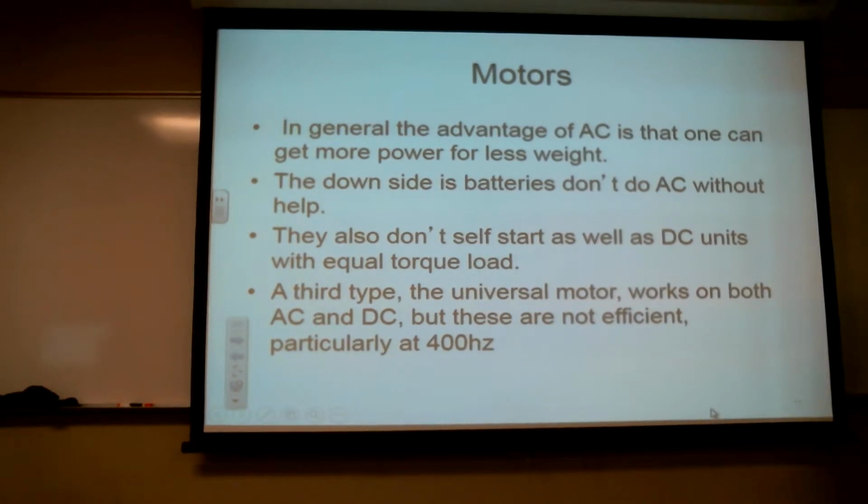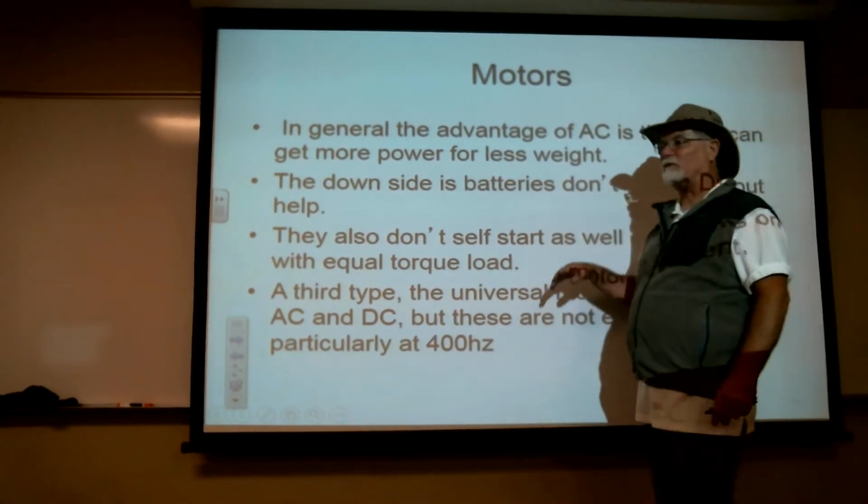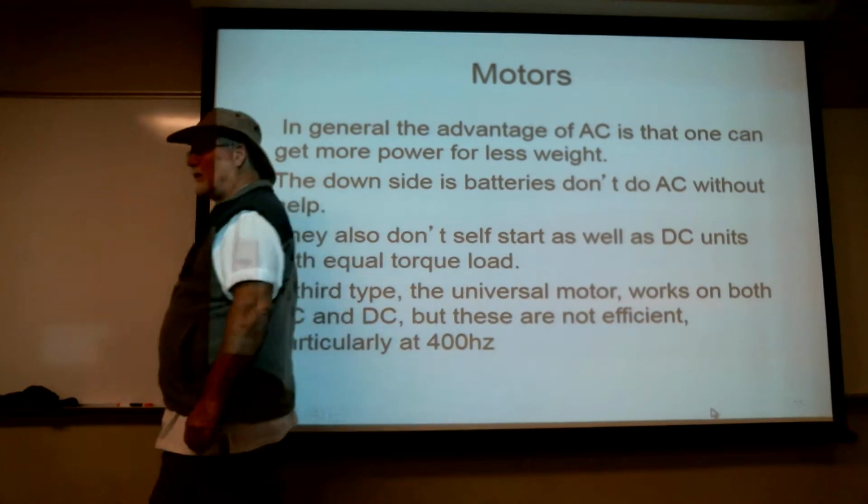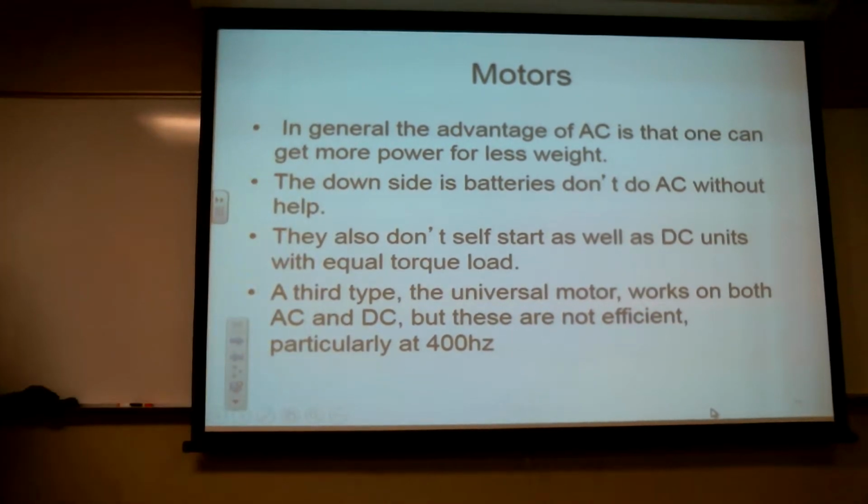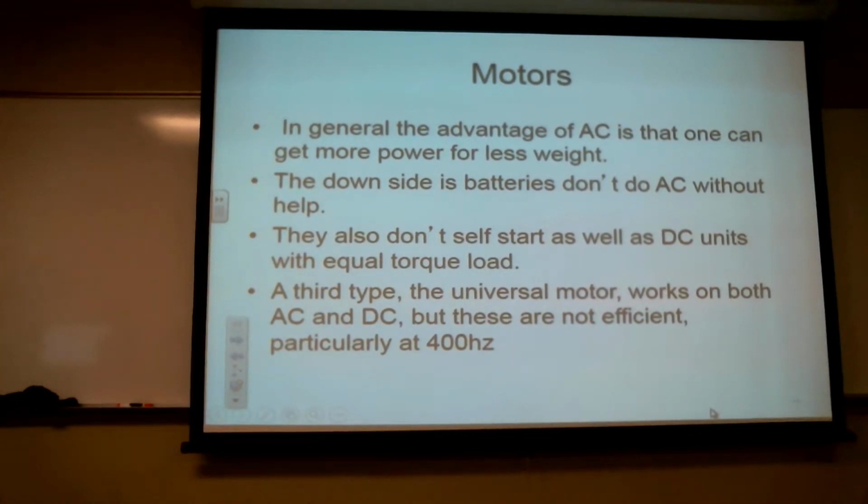So obviously the downside of AC motors is they don't work so well with batteries. If you need a lot of torque or you need to run it with a battery, AC isn't a good option. If in fact you can run with AC, and particularly you can start it somewhat unloaded, then it's by far and away the best option.